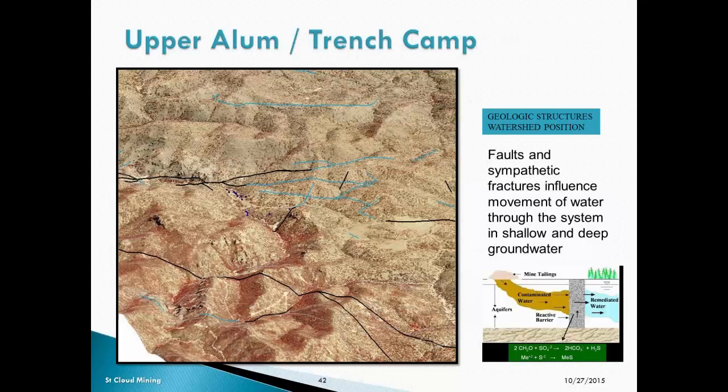And the geology was such that we were trying to figure out a way to resolve this, and we looked at the concept of passive barriers in different types of streams. So we were using a model of gabion walls, or gabion dams, holding a bed of zeolites behind them. What we couldn't deal with was the fact that there were all these structures out there, so we just had to be able to locate in the streams where the water came back to the surface and expressed itself.